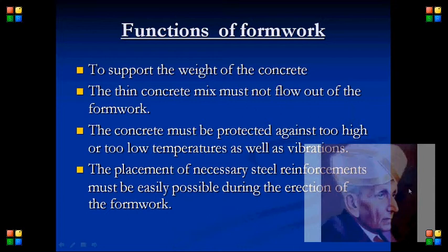Functions of formwork. To support the weight of the concrete, the thin concrete mix must not flow out of the formwork. The concrete must be protected against too high or too low temperatures as well as vibrations. The placement of necessary steel reinforcements must be easily possible during the erection of the formwork.